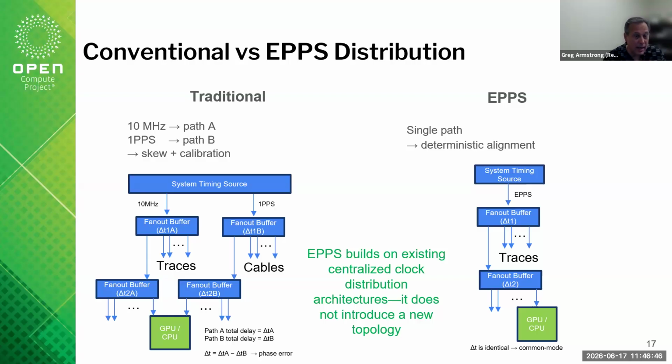So these are the things that you get with cables, right? When you look at connectors and traces and all that, a lot of that stuff is better confined, right? Your connector pins are all within the same length because the spec defines that they have to be the same length, right? So you know exactly what sort of characteristics you're getting over the connector. Most traces are known, or you can define worst case traces of how long they're going to be, right? And if you want to eliminate that, you can use fan out buffers. They even have zero delay fan out buffers where they try to make sure that the phase relationship as that fans out is maintained. So that's like zero propagation delay as reconstructing that clock, right?